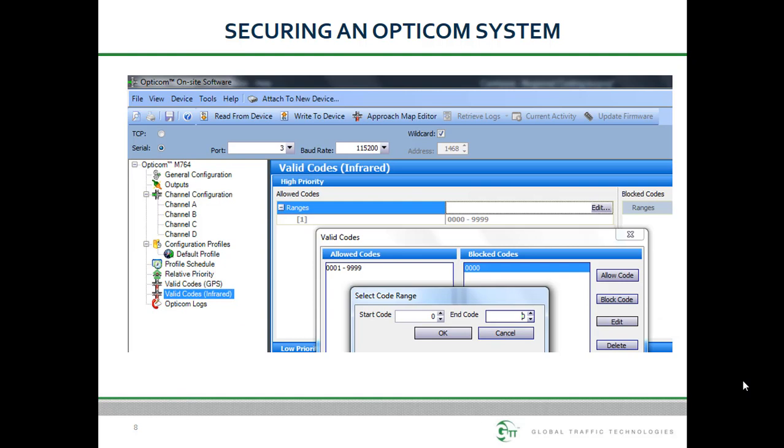Finally, let's review the role of the phase selectors in establishing a regional coding scheme. For applications that only require vehicle identification, no programming is required on the phase selector once the vehicles have all been properly programmed. Within the Opticom logs, vehicle ID fields simply appear. Optionally securing an Opticom IR or Opticom GPS is where phase selector programming applies.